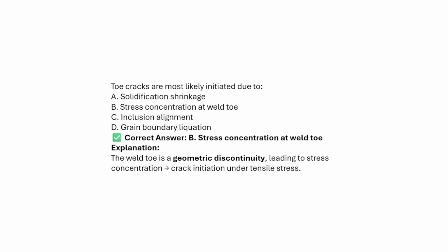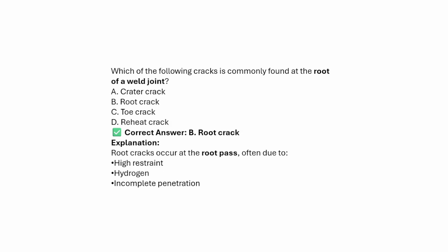At the toe region, during solidification, there will be the maximum amount of stress concentration, which results in the formation of this kind of crack. The weld toe is a geometric discontinuity leading to stress concentration that results in crack initiation under tensile stress.